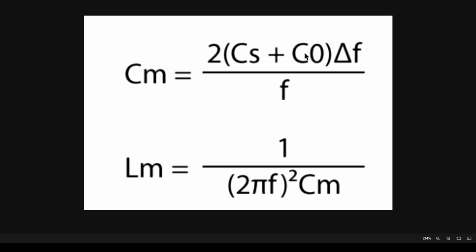For the crystal itself, you need to check that with an LCR meter or some kind of meter to check capacitance and get that value. You need to know exactly what capacitance you've got in series with the crystal in the circuit as CS. You want to use a meter and make sure you don't trust your labeling, because it's pretty critical. So make sure you know this.